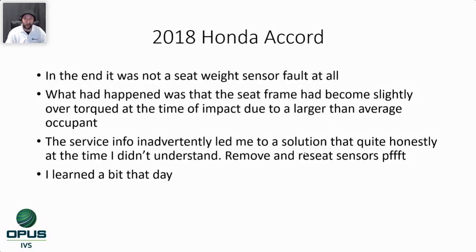So taking a quick look at that, I realized, oh, you know what? I know what happened here. We had a larger than average person sitting there as an occupant, and during the time of impact, we torqued that seat frame very slightly. It shifted very, very slightly, even though it's bolted down. That's a lot of weight to be restrained in a frontal impact. So service info inadvertently led me to a solution that, quite honestly, at the time I just didn't understand when I first read it. But yeah, sure enough, I learned a bit that day.